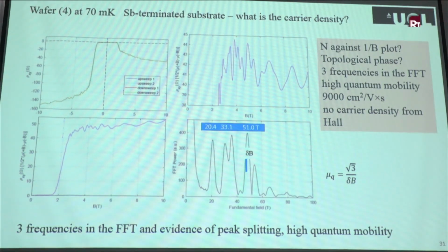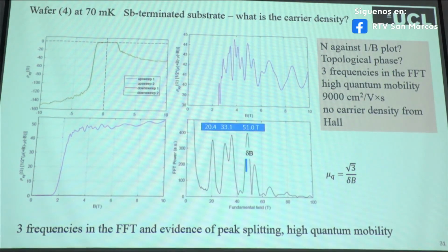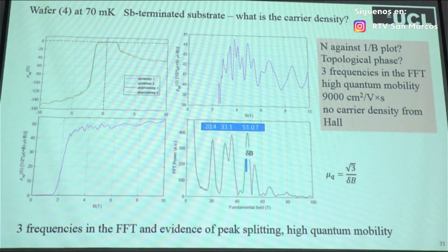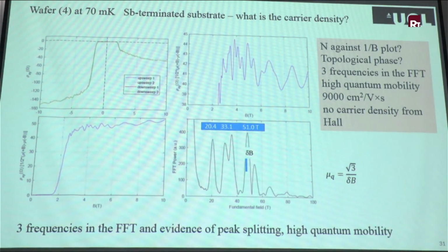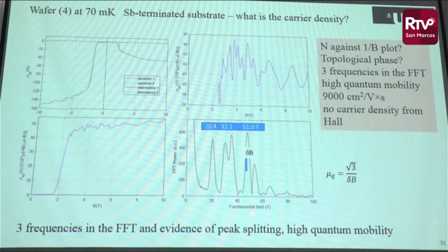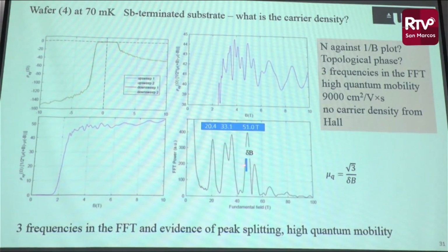And it did occur to me when I was doing this measurement, it's very good actually because the characteristic impedance of the device is 50 ohms. Most electronics, your lock-in amplifier, your preamplifier, they all want to see a characteristic impedance of 50 ohms. This material has that, so we were very, very lucky. Very clear Fourier transform. This is the bulk state. This is a topological surface state that we know has this Berry phase of pi. This state here, we're not sure what it is, but it's very clearly split.